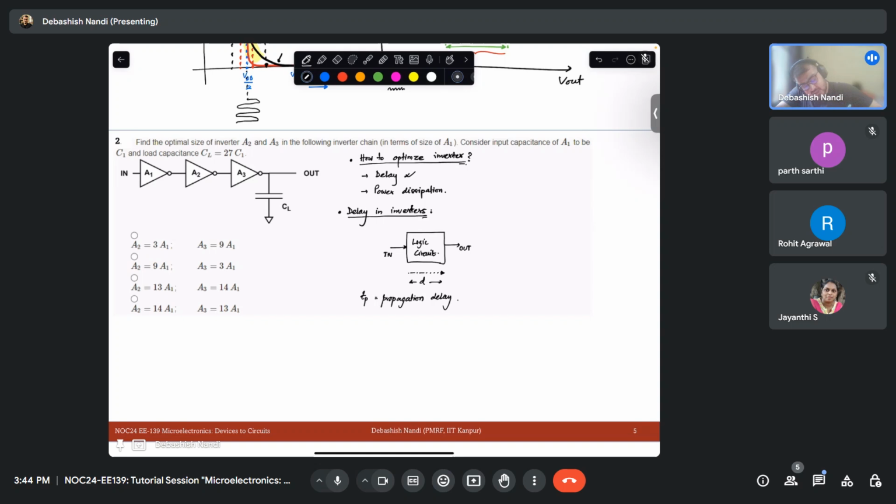Let me ask you another question. So this is a capacitor, okay? And now you are given an input signal like this. What will be the output characteristics? Like a ramp signal. Why do you say so? Because integration is there. Storing element. So at t equal to 0, what will be the slope?